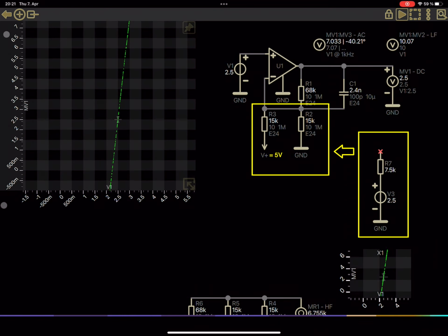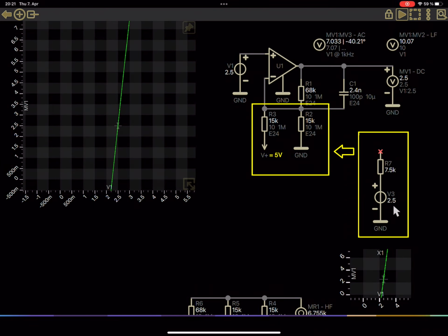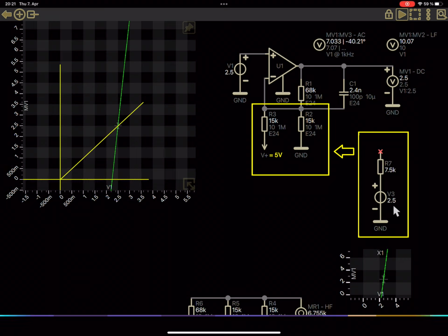Finally, as an important fact, it should be mentioned that the temporary reference voltage we have used to introduce an offset always equals the point where the DC transfer curve crosses the first median. Or in other words, if the input voltage equals the output voltage, then the input voltage also equals the required reference voltage. This is true for both the non-inverting and inverting operational amplifier circuit.